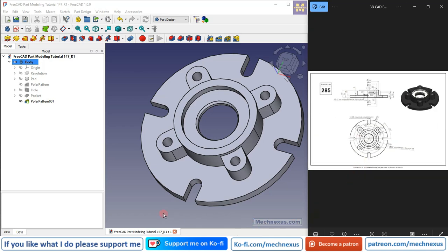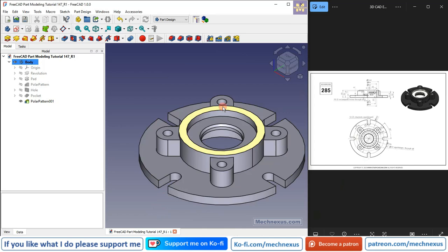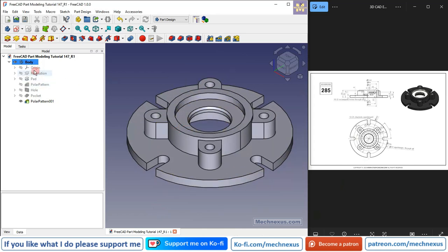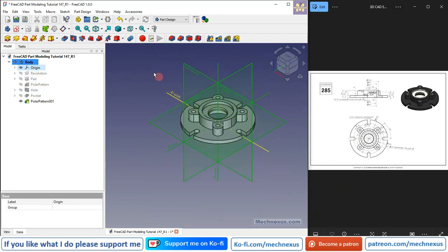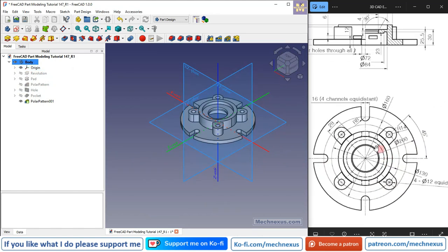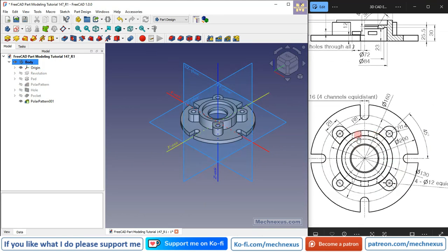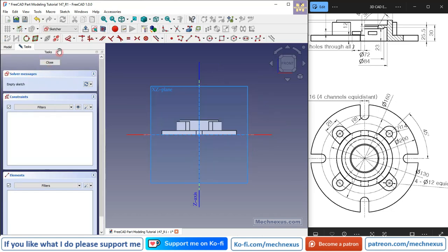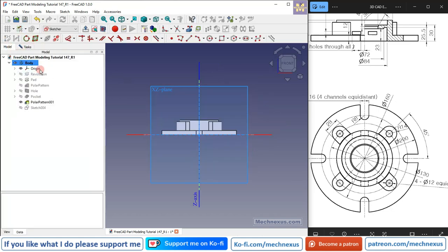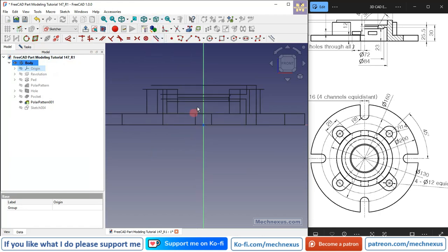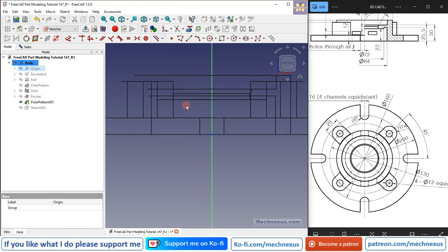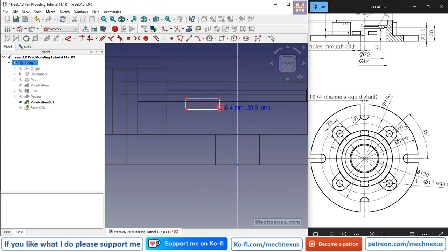Now for this we will simply press our model to the isometric view and we will turn on the origin plane. And now if you see the orientation, this is the cut which will become on this exit plane. So select the exit plane and click on the sketch, and for better sketching I will turn off the origin plane, and from here I will switch to the wireframe view so that I can draw it. So first thing is to select a rectangle tool and create a rectangle.